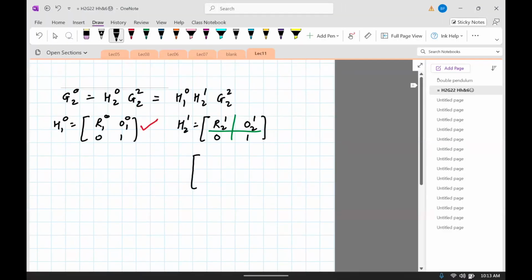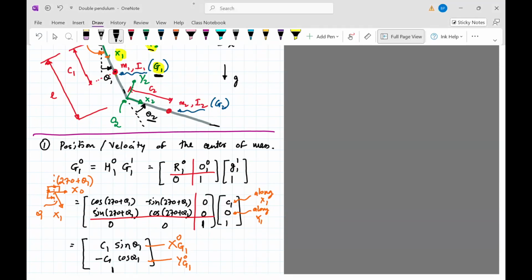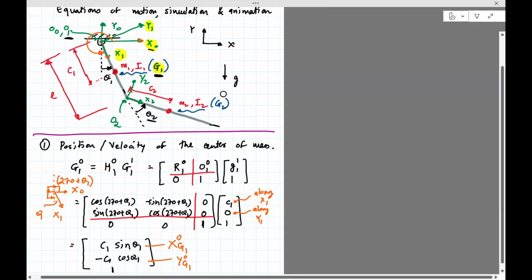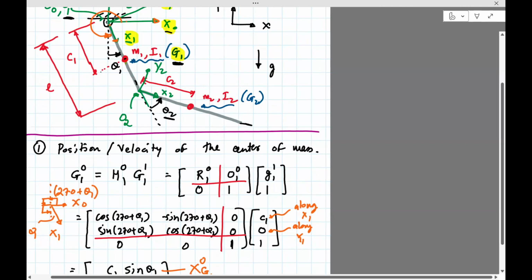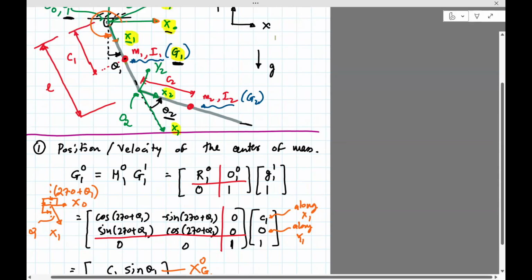R21 is going to be the angle made by link 1 with link 2. So this is link 2 and that's link 1. Using the same idea, we have x1 here. This is the axis x1. I just extended it, and this is x2. So x2 is here, x1 is here. I always go from x1 to x2 in the counterclockwise direction. In order to do that, I need to sweep through θ2, right? The angle between x1 and x2 counterclockwise is actually θ2. So that was super easy. It was not as complicated as this one.